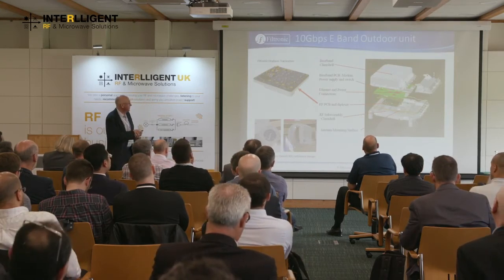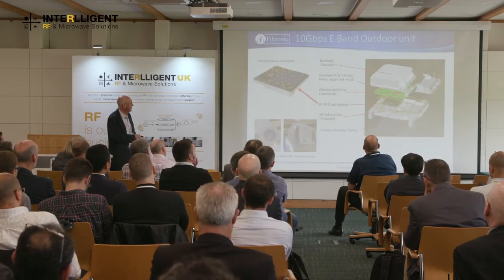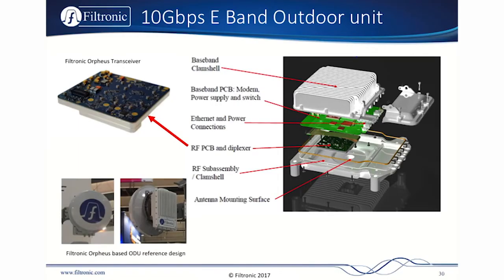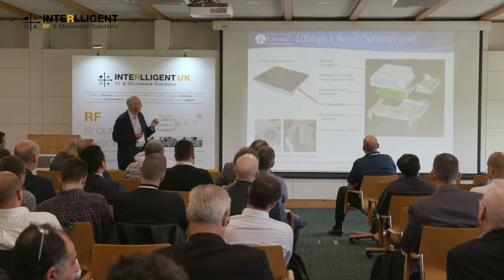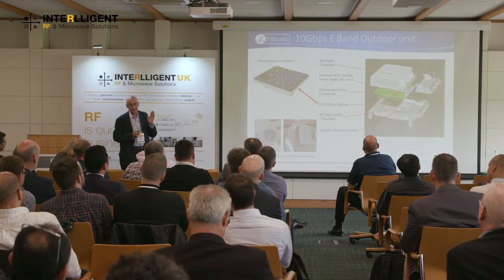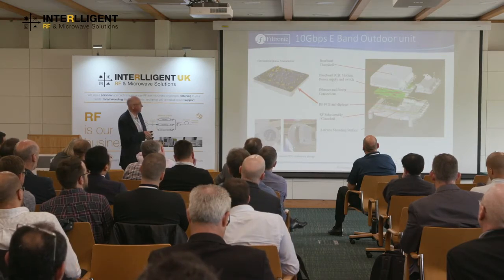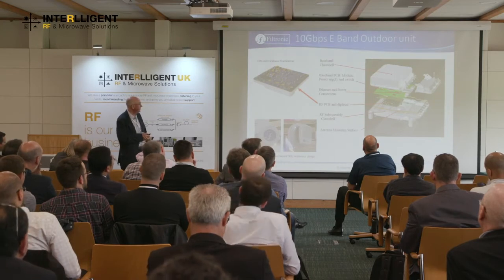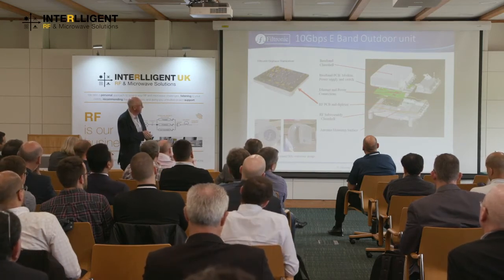Yeah. All right. So this is the insides of a transceiver. The unit here is the transmit unit. This contains the transmitter, the receiver, the diplexer, the VCOs, the PLL. It also has a microcontroller in there. And the microcontroller is used to set the frequencies. At E-band, we work on a predefined range of frequencies on 250 megahertz center frequencies, the 19 channels over each of the E-bands. So this takes care of all of that.